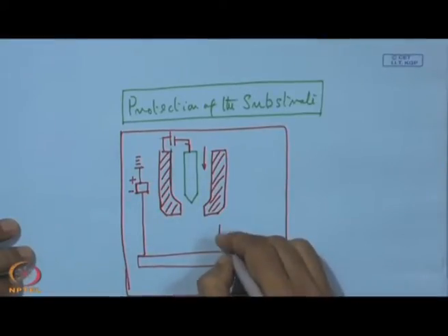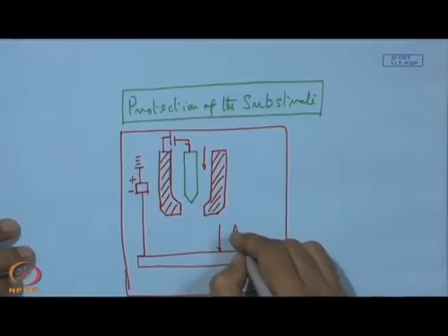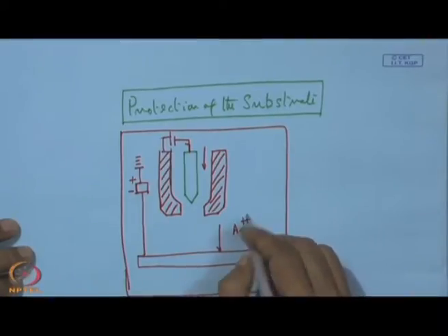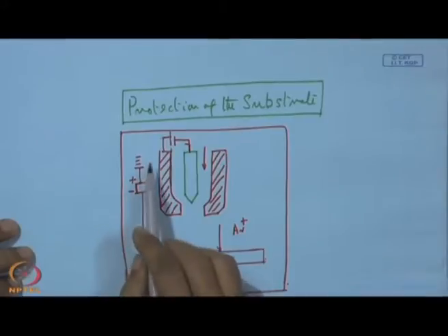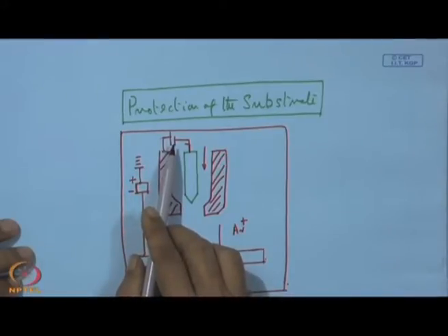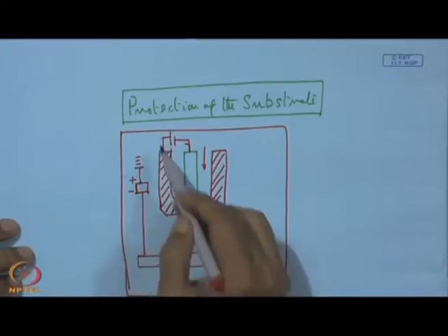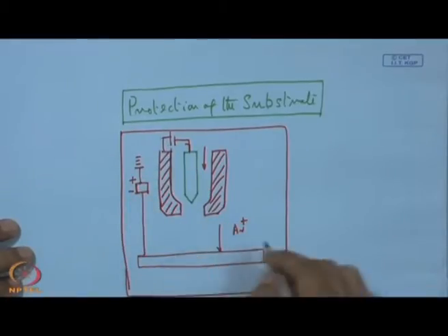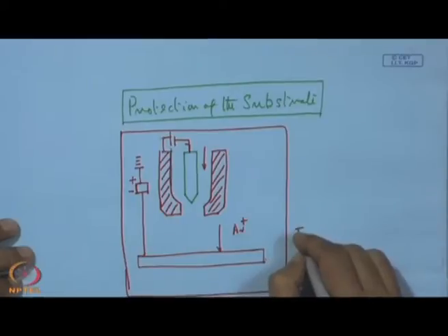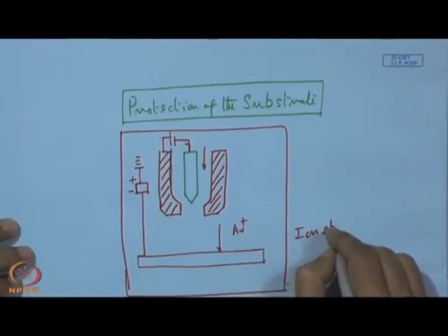In this case the argon ions will impinge on this surface and clean it, and after this cleaning we can switch over to a negative polarity. So, now it should be negatively polarized and this is actually the ion etching process.